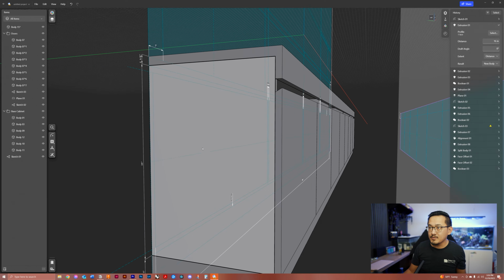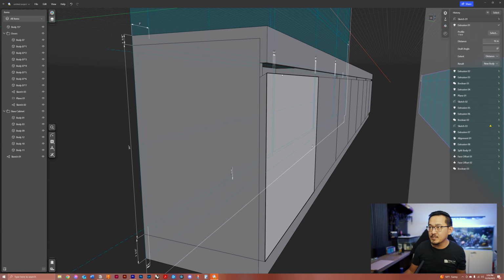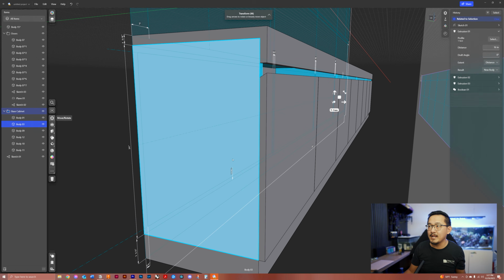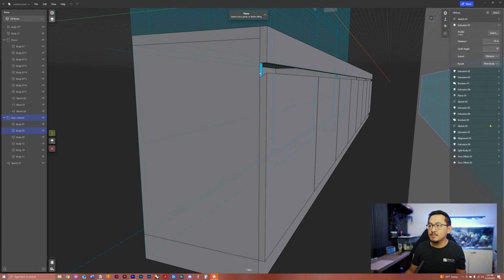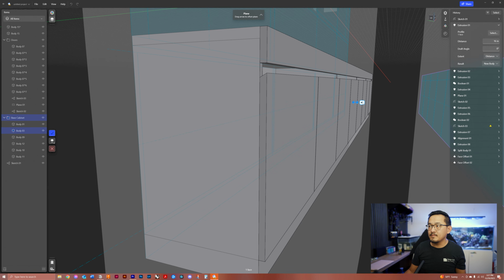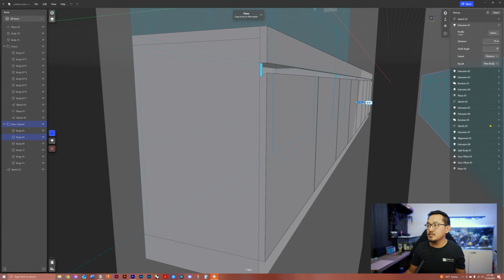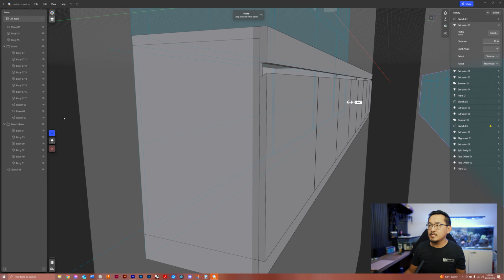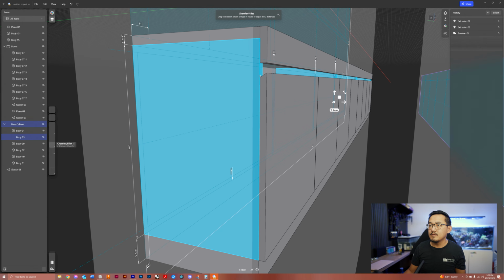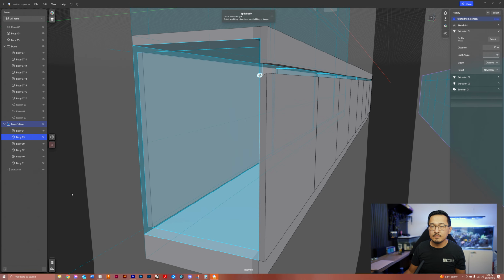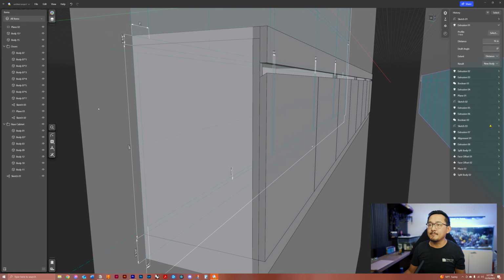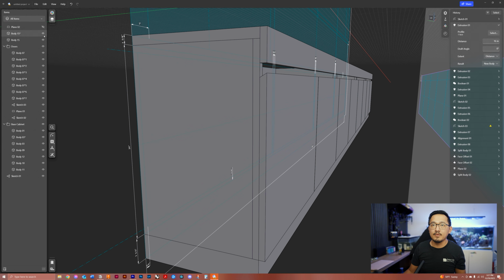So what I will also do now is, since there's this little gap and visually you're not supposed to see all the way into the cabinet there, I need to create a face frame. And for this, we're just going to add our construction plane, and we're going to move this back 3/4 of an inch in the negative direction. And then we're just going to select our entire lower cabinet body. We're going to hit the split body, and we're going to use a plane to split it. Now we can go ahead and hide our plane.